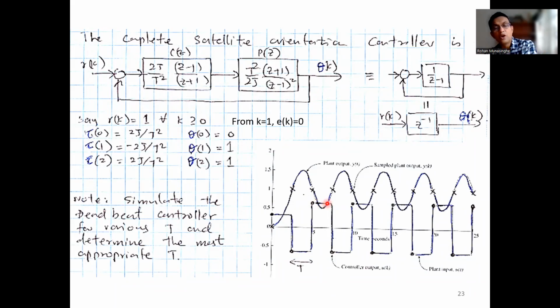You can keep going like that. And the next time step, right, tau equals 0, 1, 2, and 3, when k equals 3, it will be negative 4, right? And the next time step, it will be positive. So you will see this kind of control signal. It goes positive ceiling, negative ceiling, positive ceiling, negative ceiling, like that. This is what is called the deadbeat, right?